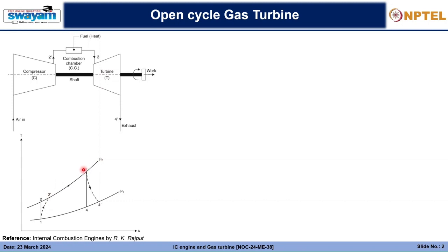That is, the enthalpy increases, and some amount of heat energy is imparted to the whole mixture, that is the gas at the inlet of the turbine, that is 3. So point 3 at the inlet of the turbine is the maximum temperature achieved throughout the whole cycle, and the gas when it enters into the turbine, it follows again.